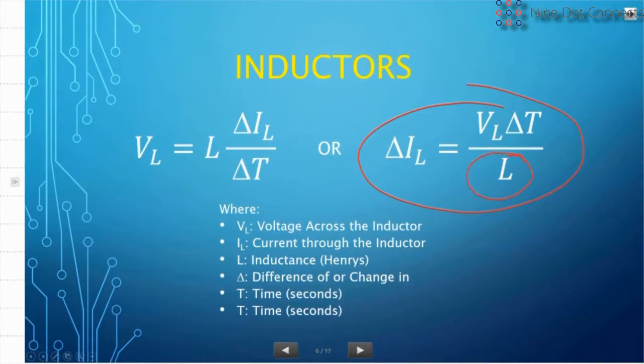Okay, you can rearrange that equation to say that if you're actually starting to change the current through something, the rate of change of current with respect to time times the inductance will give rise to a voltage. So if you had a current source that was squirting a varying current into an inductor, well, then you could say what voltage would it be developing across that inductor? It's kind of like if you're saying you have current going through a resistor, what voltage would it develop? The same thing is true with a current going through an inductor. It's only that it's sensitive to the rate of change.